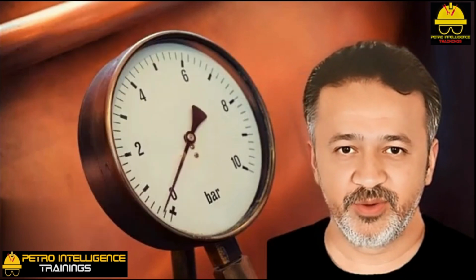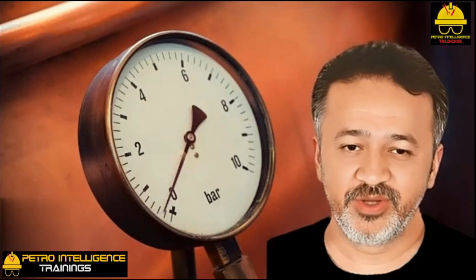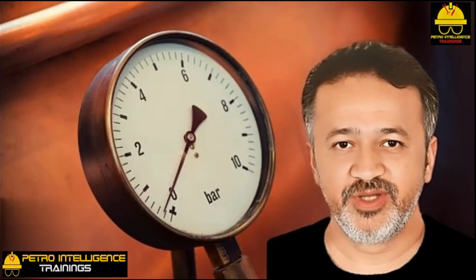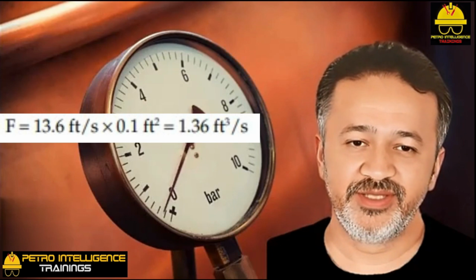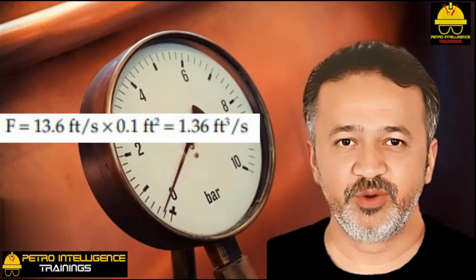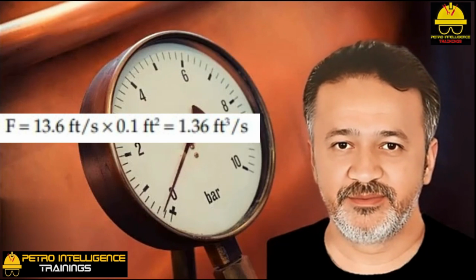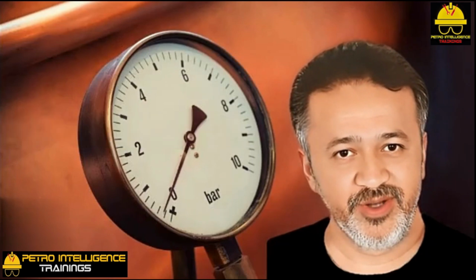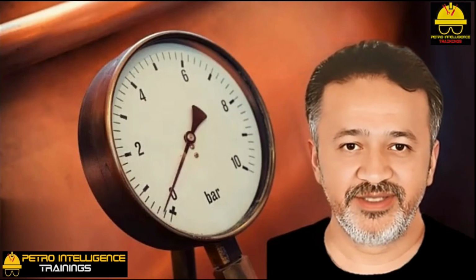We find the volumetric flow rate, F, in cubic feet per second after multiplying by the cross-sectional area of the orifice opening. Thus in this case, F equals 13.6 feet per second times 0.1 square feet equals 1.36 cubic feet per second. You may notice when you measure delta P that it is a small value, difficult to measure accurately.